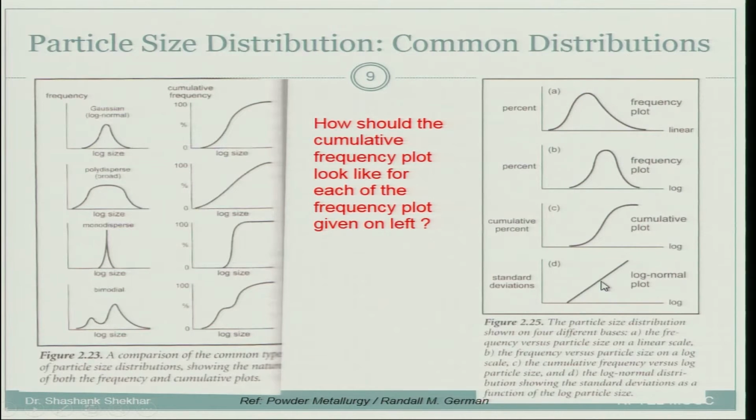Now, if you go to +1 standard deviation and -1 standard deviation, then over here it will be D50 plus 32, so on, it will be D82, and here it will be D50 minus 32, like D18. So, D18 to D82. This is how you can always draw a corresponding diameter which represents how much fraction of data lies below this, and plot it against the number of standard deviations.